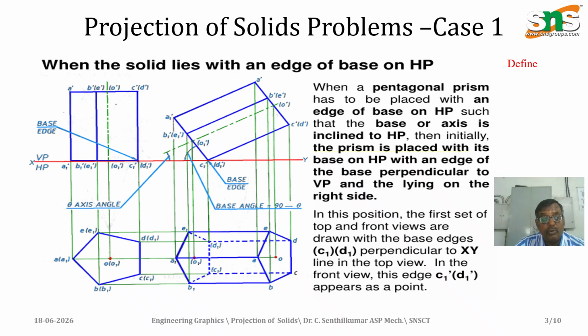In the top view here, we will see the face, that is the top face of the pentagonal prism. That pentagonal prism we draw. Whichever edges are not visible will be made as dotted lines. You can see the pentagonal prism here, one side of which has a dotted line, and another side edge is also shown as a dotted line.